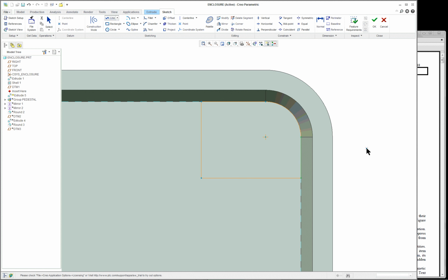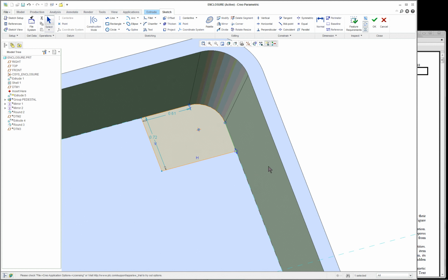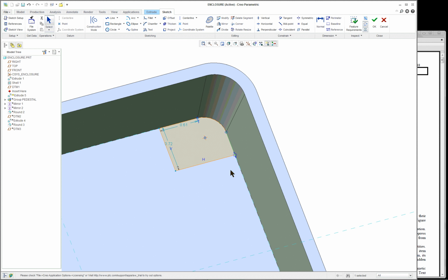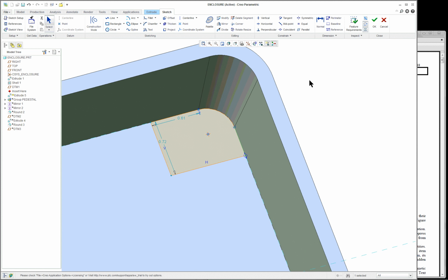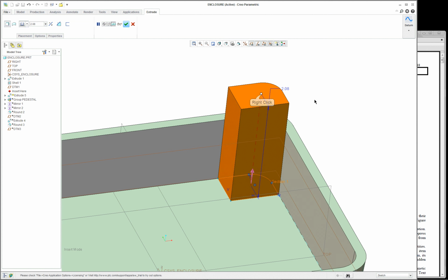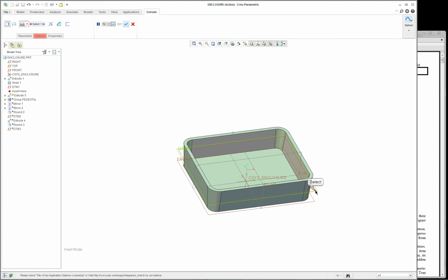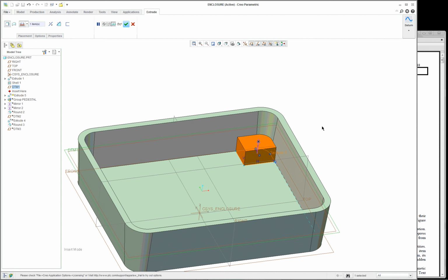I want this to be a shaded feature here. So in this case here, you see we use these edges as references, and then we did put the geometry in and locked it in. Check. Let's project up. And in this case here, that's why we want this datum plane, because we want to go up to it. So, 2 selected, and we want to select the datum plane. That'll control the height of it.